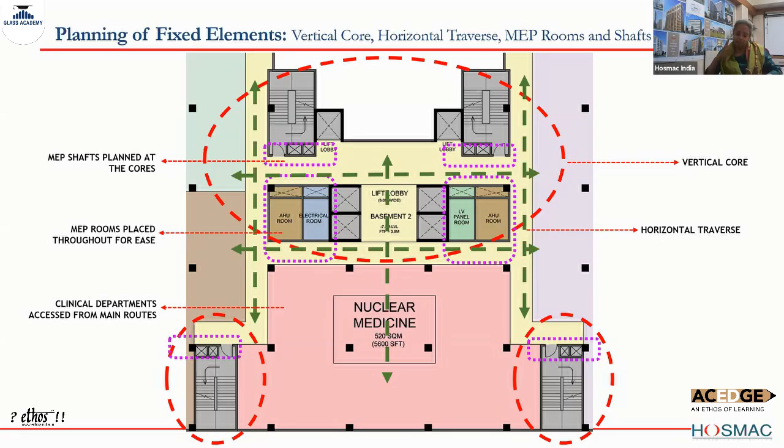That means a middle breaking distance of 22.5 meters is where a person should be able to run to the nearest staircase for a fire exit. So this is a meandering run. It's not the way the crow flies, okay? So this is also something which one has to take into consideration. Distance between 2 staircases is 45 meters in a sprinklered building.